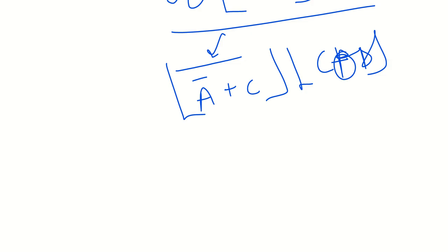Okay, and one thing is they are multiplying. They are AND gates. So it means that this whole thing has to be 1 and this whole thing has to be 1 so that the whole function goes to 1. One of the shortest ways: realize that C XOR D will only be 1 if either of them is 1. If both of them are 1, you will get a 0, which will make the whole function go to 0. So if C is equal to 1, D has to be 0. And if C is equal to 0, D has to be 1. So those are the possible values for this one.